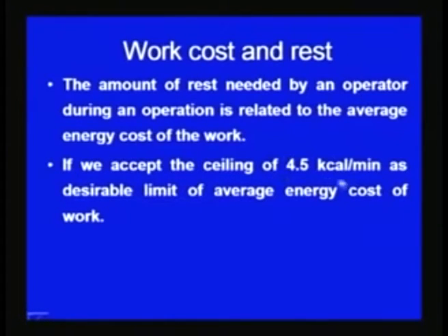Normally, an energy cost of up to 4.5 kilocalorie per minute is considered as the upper limit of energy consumption which a worker can deliver without the need of a rest. If we accept the ceiling of 4.5 kilocalorie per minute as a desirable limit of the average energy cost of the work, then this is the limit of energy which a worker can deliver continuously without a break.